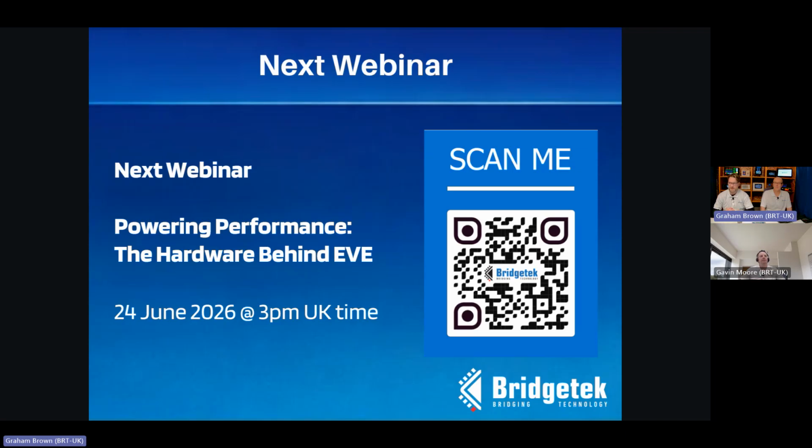You would compile an application which issues screens to the device over SPI. And these screens are contained in a stream of SPI bytes that you would send to EVE. EVE then generates the screen content based on these commands. So the idea is that it offloads the computational effort required to generate screen content from your MCU.